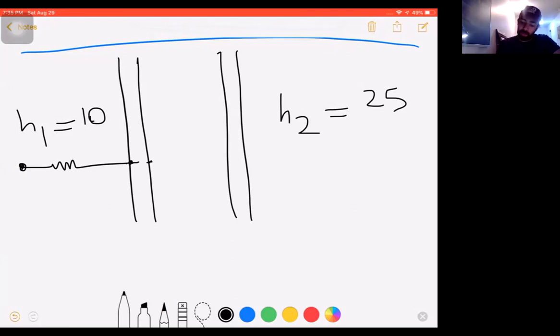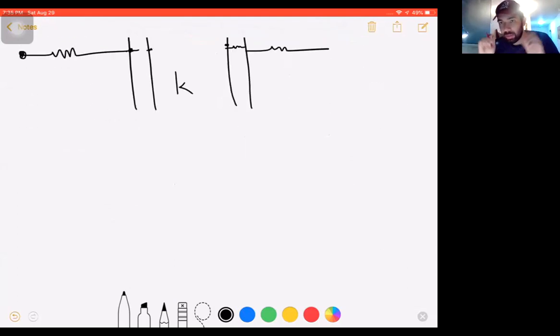Then between the 2 glasses, there is an air insulation layer with a specified K that is much lower in magnitude compared to the constant we have for the glass layers. Again, similar resistance for the outer glass layer, and the convective layer at the end. So basically, there are 5 layers.